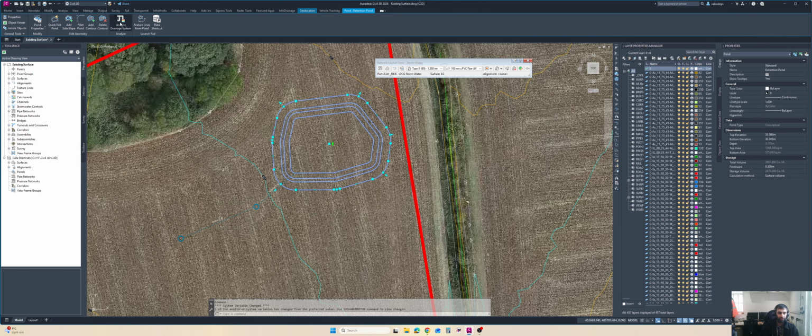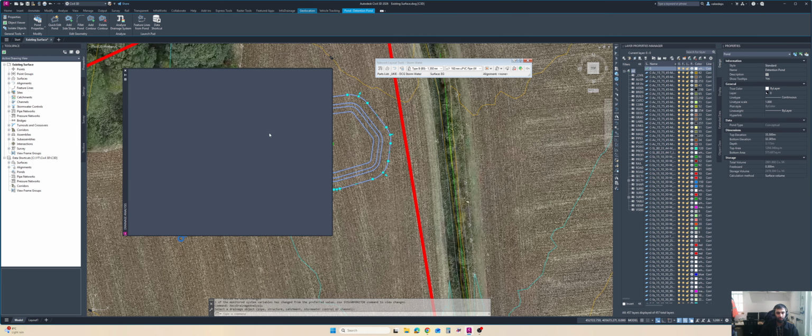This one also has the drainage system, but actually mostly the analysis I do is in InfoDrainage, but you can also do it, I think, here. But you need to have your catchments and your rainfall runoff data, and then this can be done in Civil 3D, but mostly I prefer InfoDrainage for all my hydraulic analysis.